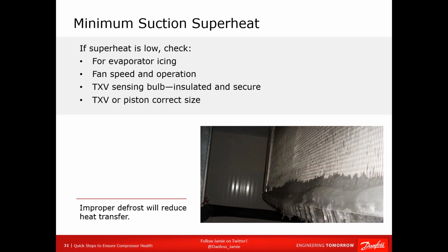And once ice starts to build, then you have a problem because the ice acts as insulation. And this drives the temperature lower and lower, and eventually you don't get enough airflow through there, causing low heat transfer. Fan speed and operation.